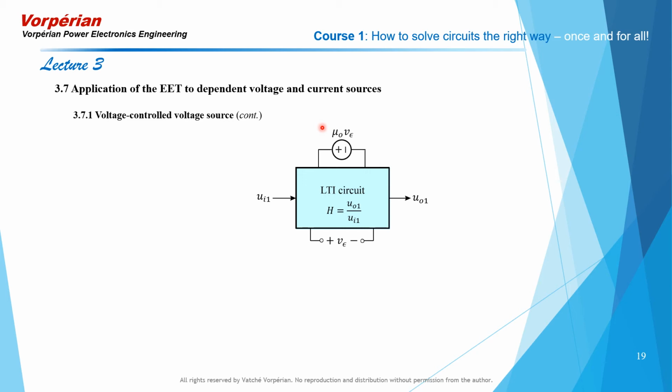We have two choices. Either we set mu0 equal to 0 at first, or we set mu0 equal to infinity. We will try the second choice first. We let mu0 go to infinity, and the extra element theorem takes the following form. In it, we have h infinity, which is the transfer function mu0 over mu1 with the value of mu0 taken to infinity.